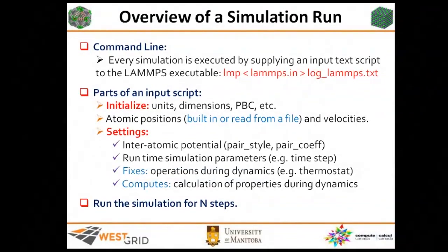For simple systems, like BCC or FCC, you can just use the command from LAMMPS to generate the initial positions. You can also read the positions from a file. If you already have a file with the positions, you can read it and use it in LAMMPS, but on one condition: you need to write that file in a format that LAMMPS can read.